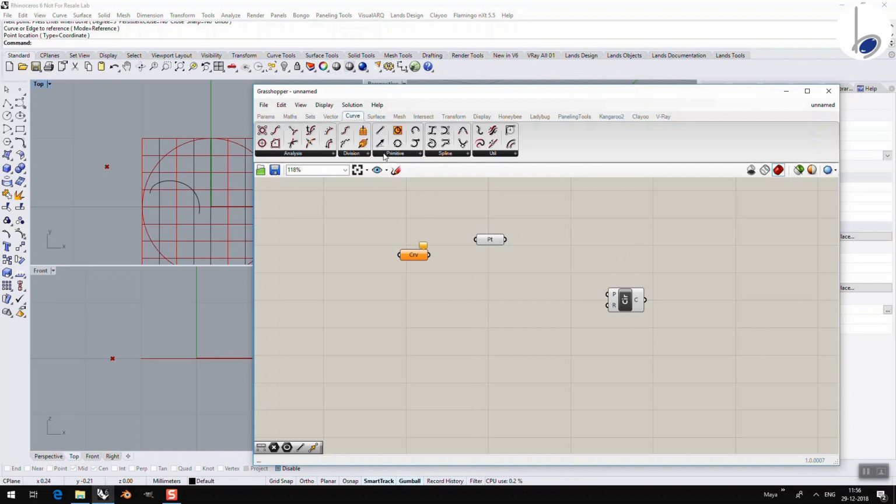If on the other hand I had gone to curves, primitives, and I had chosen a circle, tangent, tangent, where I haven't input any information, it is going to stay orange in color. On the other hand, although I haven't given any information to this circle, by default the P has a value of world XY plane, whereas R has a value of 1, which Grasshopper has defined, or rather predefined, which is why this is a stable component. So we saw two colors, orange and light grey. If I select a component, it becomes greenish in color, not only in Rhino but also on the canvas in Grasshopper.